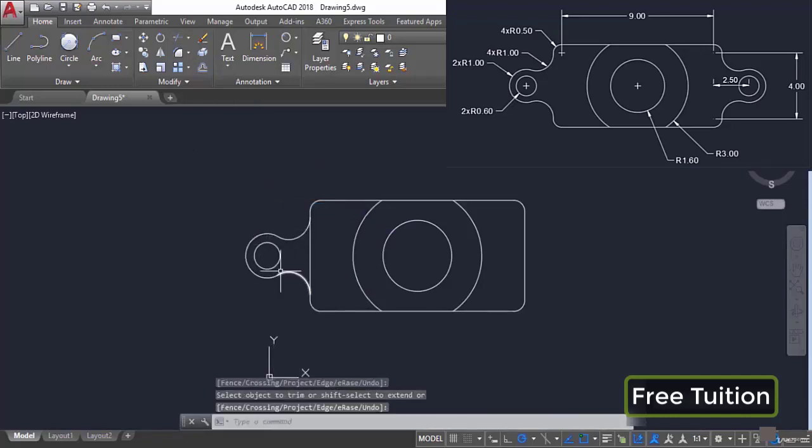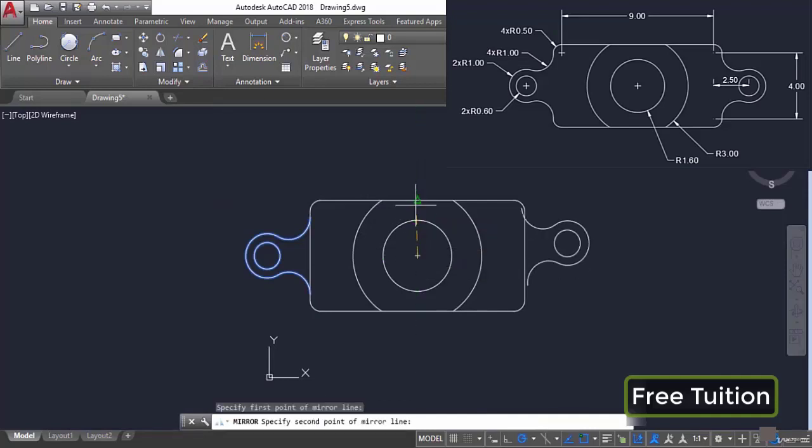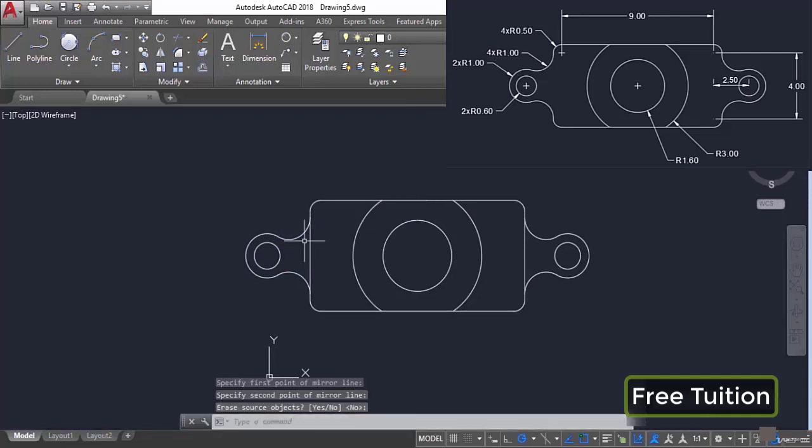Now we need to make a mirror image of this on this side. So I'll select it all, go to the mirror tool, click on the center of this circle and the midpoint of this horizontal line and simply press enter. There we have it, the mirror image. Now we need to add a final detail and we can add it by removing these two parts. So I'll go to trim, press enter, remove this portion and remove this portion and press enter. So that's the final drawing which we were required to make.